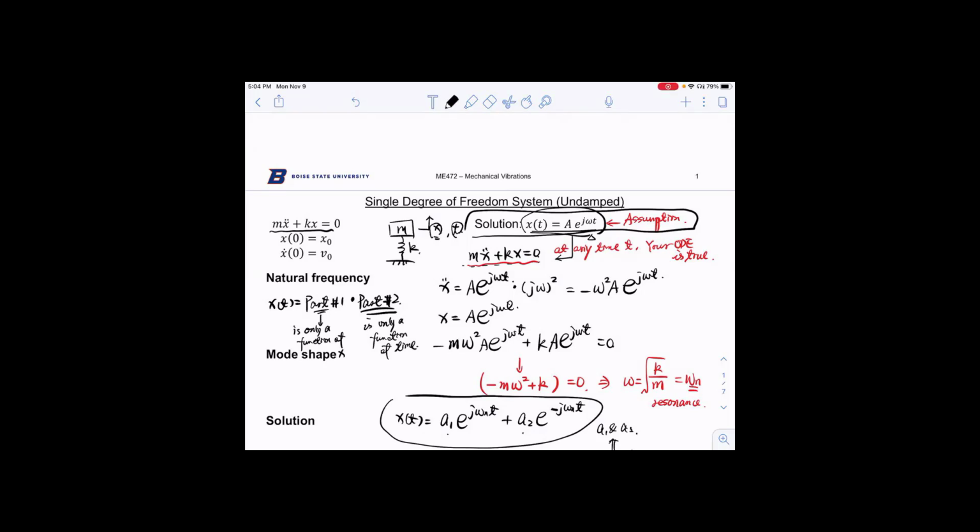So we separate these two variables. In this case, your part 1 is actually a constant. That's very special. The second one is a harmonic excitation. By using different part 2, you might have different expressions. In mechanical systems, we usually assume harmonic excitation because of the Fourier series. Any periodic signal can be decomposed into harmonic oscillation.